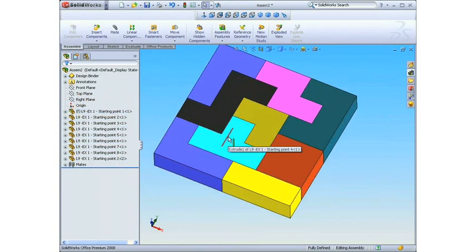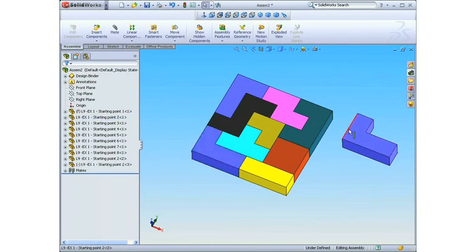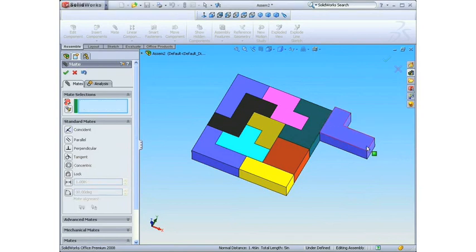I trust this example will be a help, and the multiple use of the coincident mate will help you understand how the coincident mate works. Now I would like to add one more thing though. So I'm going to drag one more part over and just point out what would happen if you accidentally mated 2 edges together, like I've done there.